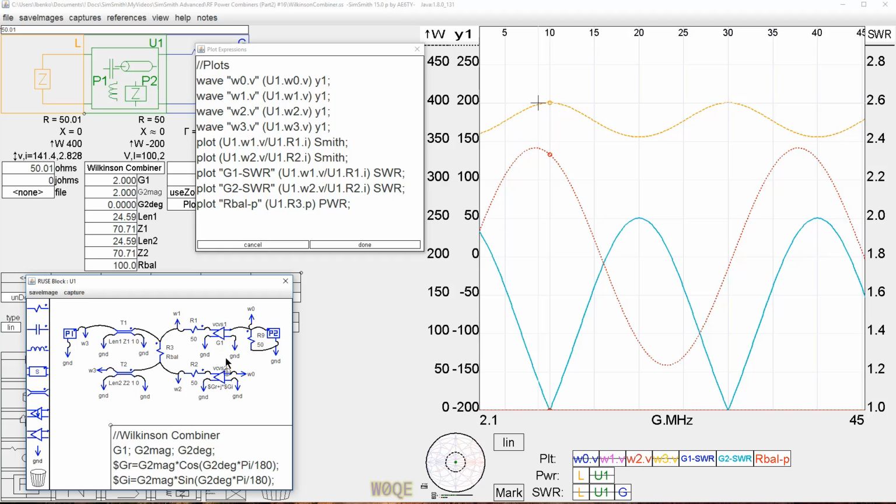If these two generators are not exactly the same frequency, the imposing of this generator's signal on this generator's output will cause this generator to produce a little bit of IMD internally. And since we're trying to measure IMD, we don't want that to happen. So in a case of measuring IMD where the two generators are different frequencies, we want an incredibly good balance.